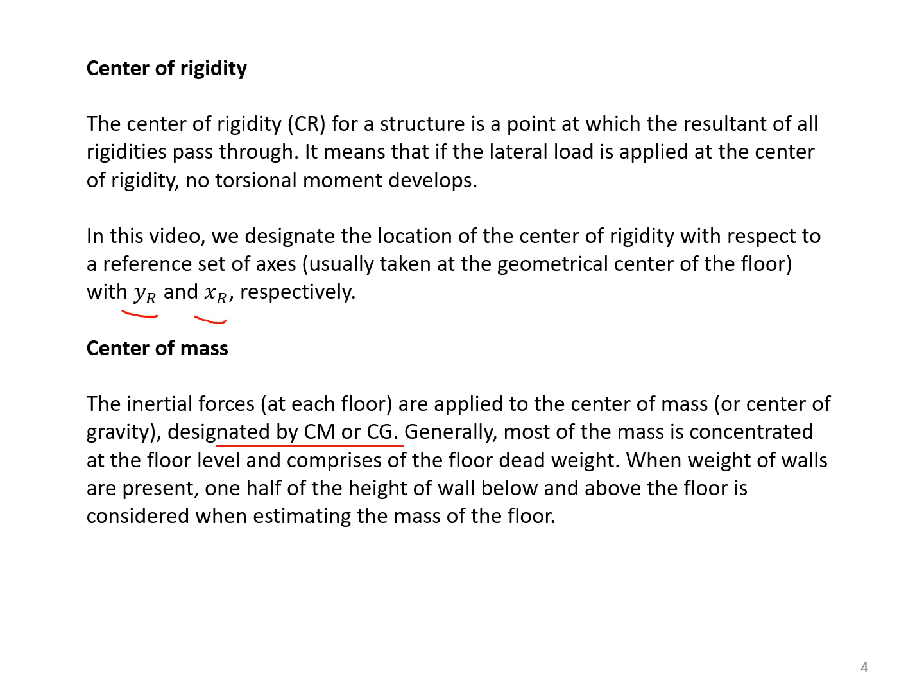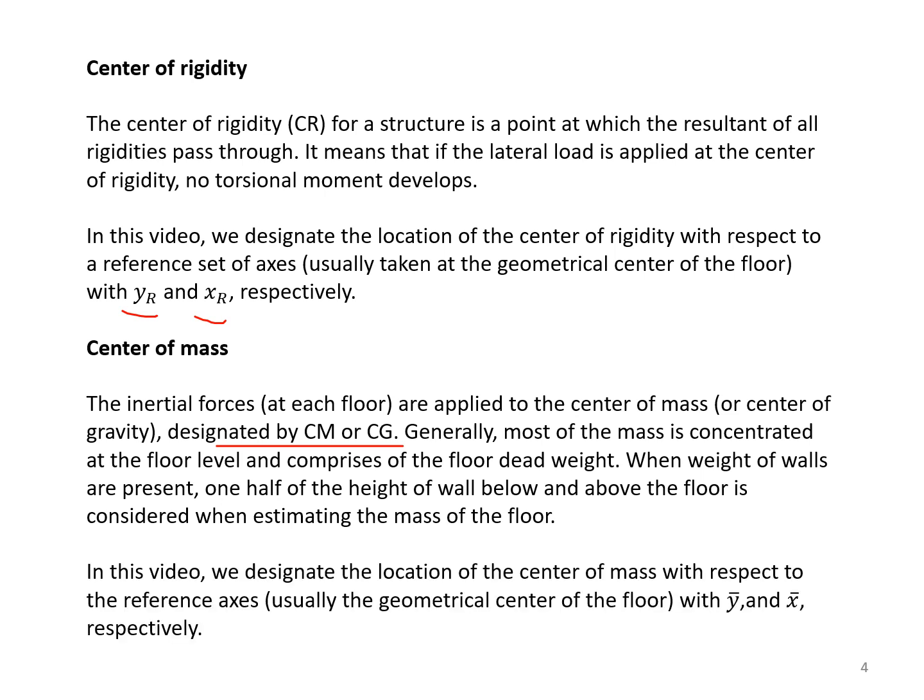When weights of walls are present, 1/2 of the height of the wall below and 1/2 above the floor are considered when estimating the mass of the floor. In this video, we designate the location of the center of mass with respect to the reference axes, usually the geometrical center of the floor, with y bar and x bar respectively.